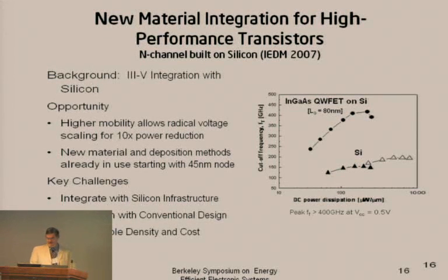Back in 2007, we demonstrated an indium gallium arsenide N-channel quantum well FET, which again has a huge saving in the DC power consumption relative to silicon. If you look at the frequency response at a given power, you see a huge differential between the III-V device and the silicon device.